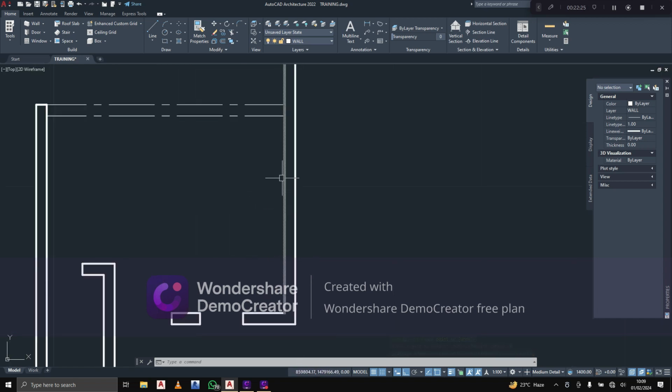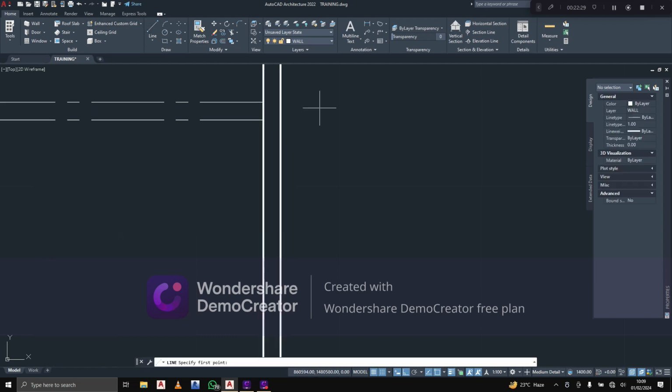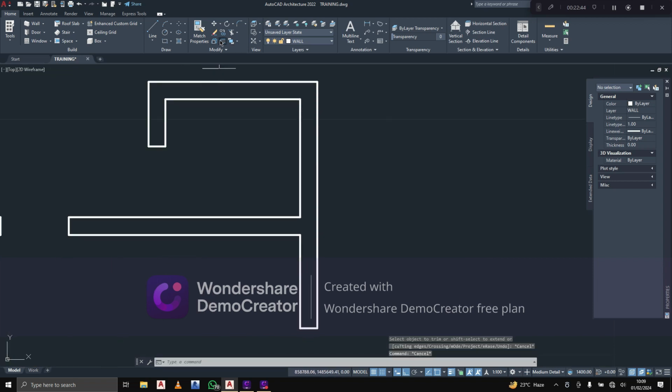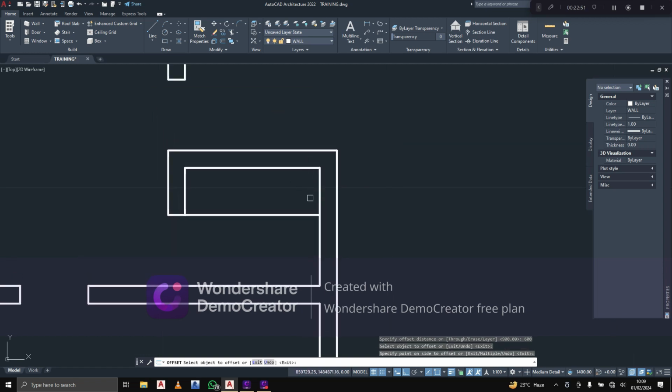So I only want to put a window at this edge. You just draw the line and offset your 900 straight. Then I want it flushed to that angle, straight, and trim it off. Good. So for the store, let's put a 600 window. Flush it to any side you wish. Let's flush it to the outside. Yes. So extend it and trim off.